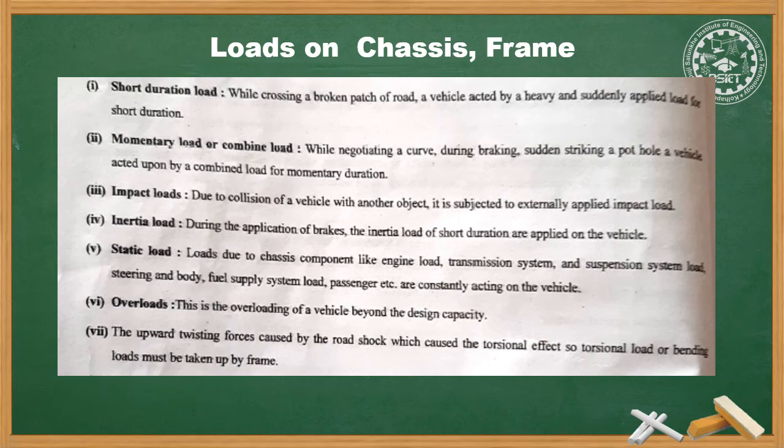Third, impact load. Impact load is due to the collision of the vehicle with another object. It is subjected to externally applied impact load. Fourth, inertia load. During the application of the brakes, inertia loads of short duration are applied on the vehicle. Fifth, static load. Load due to the chassis components such as engine, transmission system, suspension system, braking system, steering system, fuel supply system, passengers, etc. are constantly acting on the vehicle.